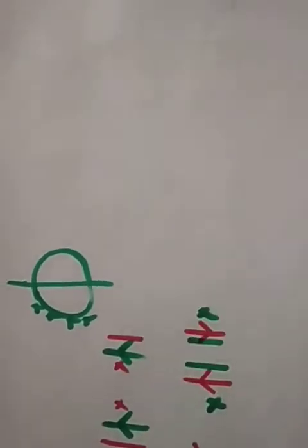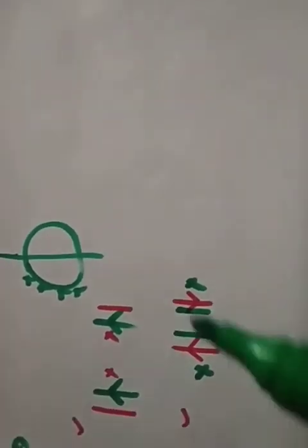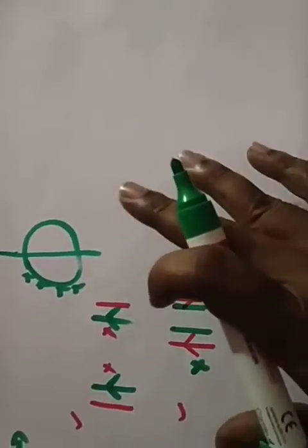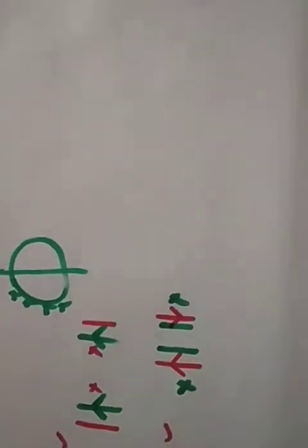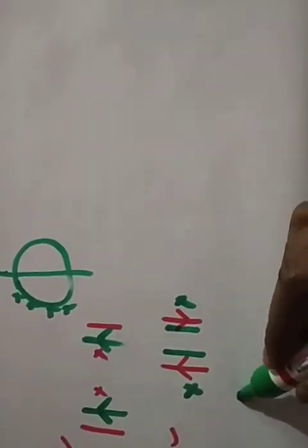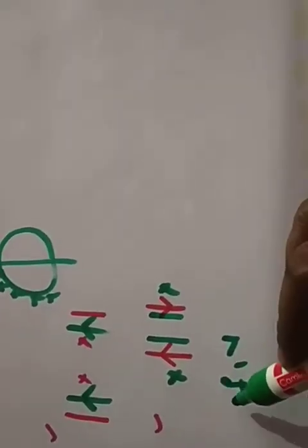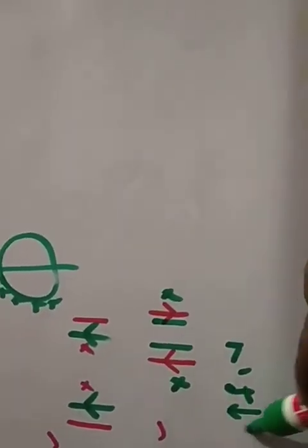After that, we discussed how to minimize the proximity effect. In order to minimize it, the distance between the conductors should be large. We can also vary the frequency or the voltage. But in an AC supply, increasing or decreasing the frequency is not possible because the frequencies are fixed in AC systems.